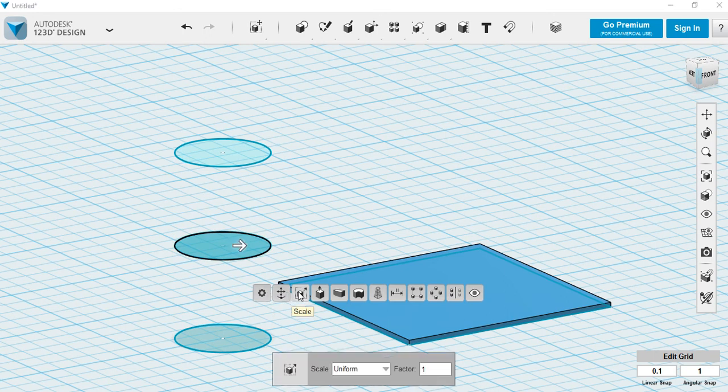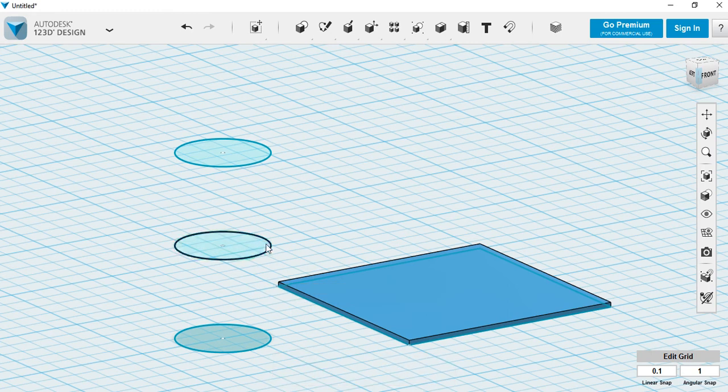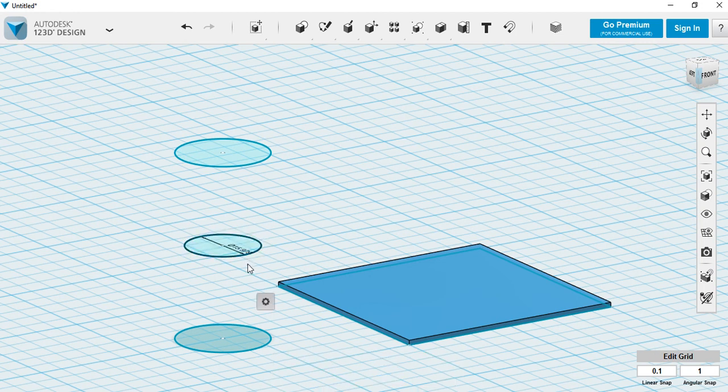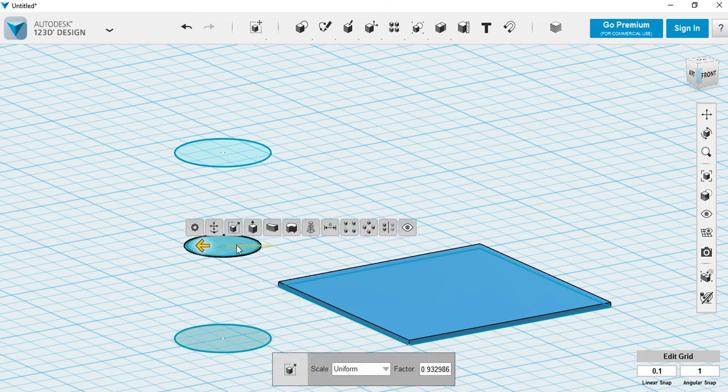With this shape, I'm going to make it thinner. I'm going to make the circle smaller. So what I'm going to do is select the circle, move to the cog and select scale and push the arrow inwards, like that. Check the measurement. I can click on it and you can see that that has a diameter now of 15. I'm happy with that. You could change it if you wanted to. Go back to scale and move it in a little bit more, or out a little bit. It's completely up to you. Click on the outside when it's done.